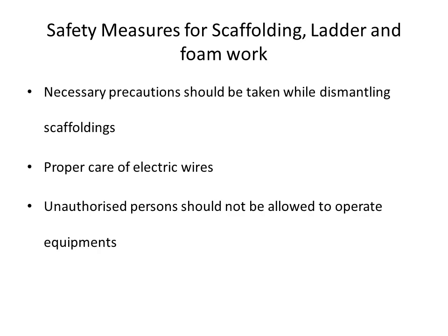Necessary precautions should be taken while dismantling the scaffolding also. When work is being performed above the scaffold platform, a protective overhead covering should be provided for the men working on the scaffolding. And also, we have to ensure proper dismantling of the scaffolding. We should take the necessary precautions to prevent injury to the workers due to the fall of loose materials and other parts of the scaffold.